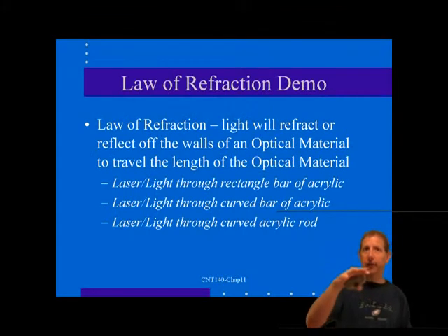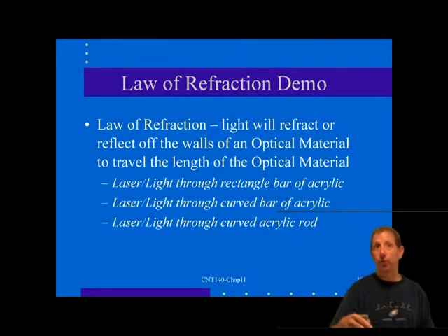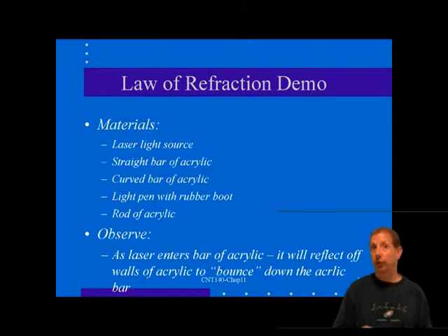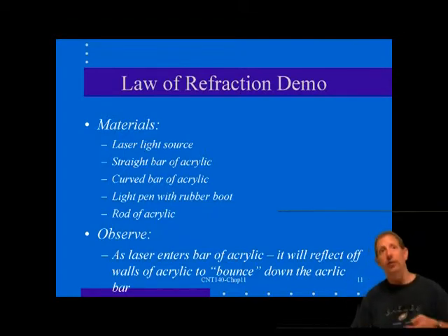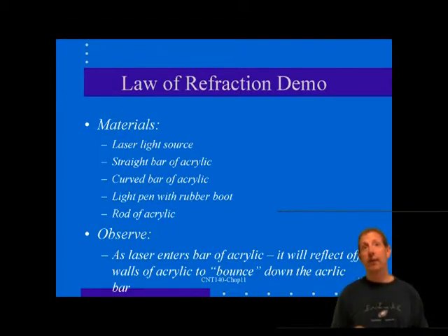Now, here's how data transmission over fiber works. A data modulated electrical signal, such as a LAN packet, is first applied to the light source, which converts the signal into light. The beam of light from the source is then directed at one end of the fiber, which transmits it through the fiber all the way to the other end. At the far end of the fiber, a light-sensitive device is used to detect the light from the fiber and convert it back to the electrical signal.